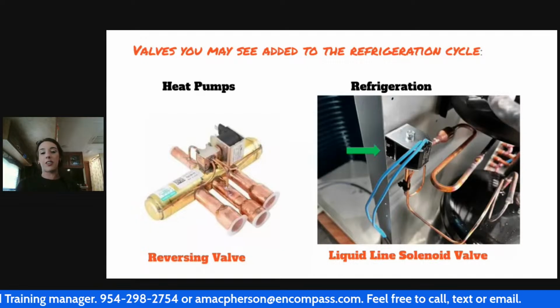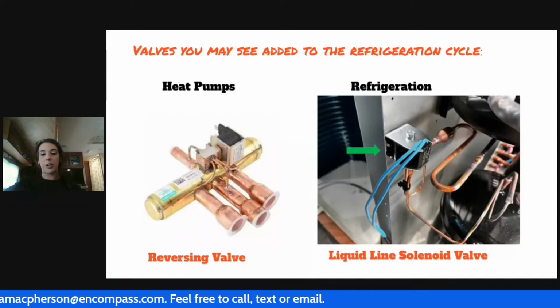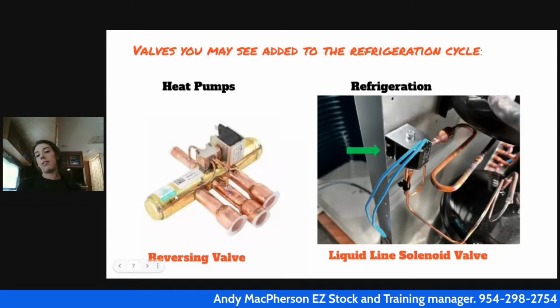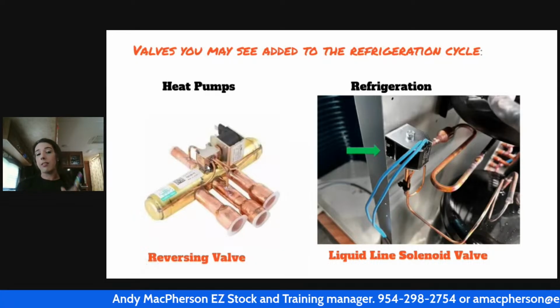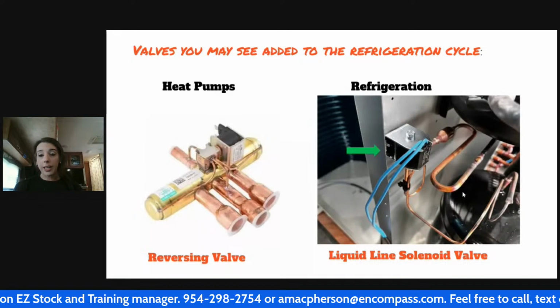Once we get to the reversing valve, we're deciding, are we reversing that entire refrigerant cycle to heat this room, or are we letting it go in the normal, typical physical way? And that's the component that decides it. But what's interesting is that's done by solenoid valve. So it's not very different from a walk-in cooler, right?